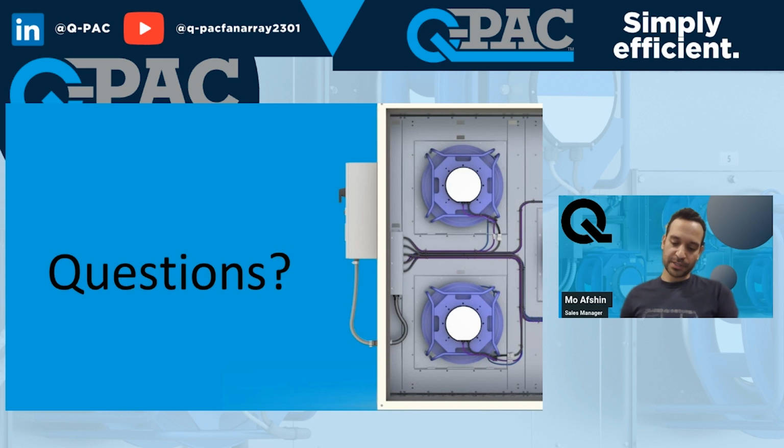It basically compares the efficiency of your fan system to a baseline fan efficiency. That baseline is a belt drive motor, and ASHRAE 90.1 basically wants every fan to be more efficient than that baseline, so they want an FEI above 1.0. So I think that's the closest we've got so far to a true wire to air efficiency comparison.